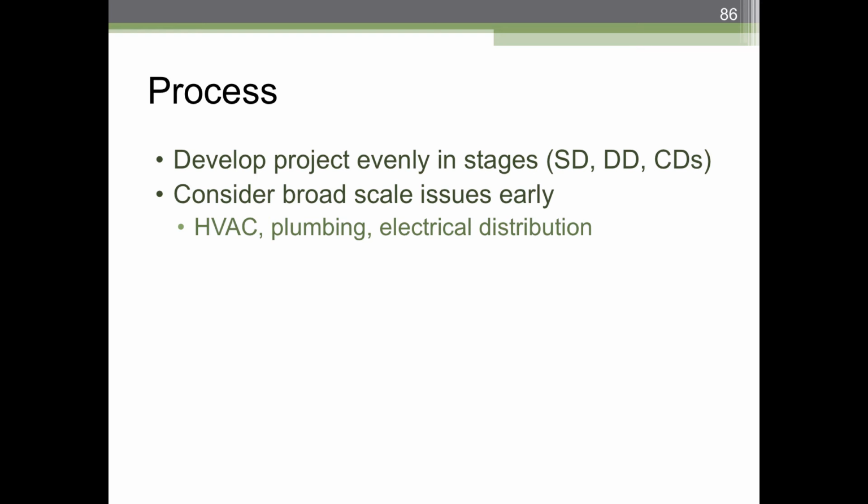Design development, you are going to want to look at specific construction systems and assemblies. For example, if you decide, well, let's go with some acoustical treatment where we hang an acoustical ceiling, design development is the point where you'd start to look at what kind of acoustical ceilings are out there. Obviously, you're going to narrow it down, not just use the Revit 2x2 ceiling, but ask what kind of ceiling is going to get us the best sound control? What kind of ceiling can handle the moisture in this kind of facility? What kind of ceiling is going to look good at the scale of this project? It's huge. Maybe something more like waves is going to be good. Well, that cuts out the traditional pressed mineral fiber ceiling, but maybe that would look better. Maybe that would have more of an aesthetic appeal.